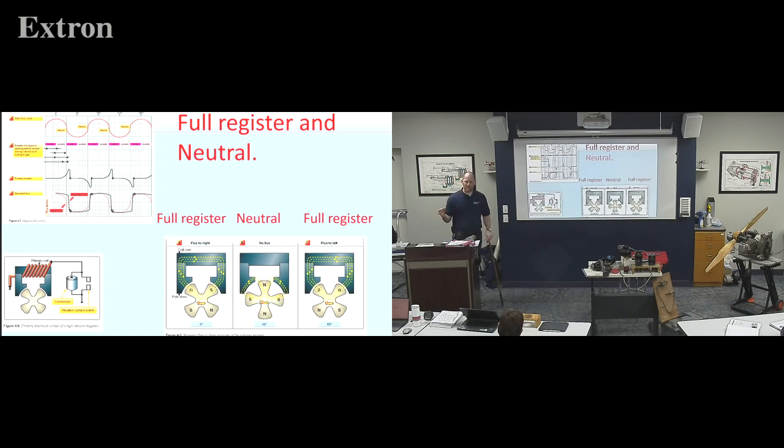We're not actually powering a device. So we're doing that through our coil. And right when the amp draw is the highest, we say, hey, I see you're really high. I'm going to open the contacts. So we open the contacts when the amp draw is the highest, and all of a sudden I go from a really high amp draw to no amp draw. That's a collapsing field, isn't it? I went from my highest amp draw to no amp draw as fast as I could by opening the contacts. Well, what's not shown in this picture is that's where our transformer is, out to my spark plug.